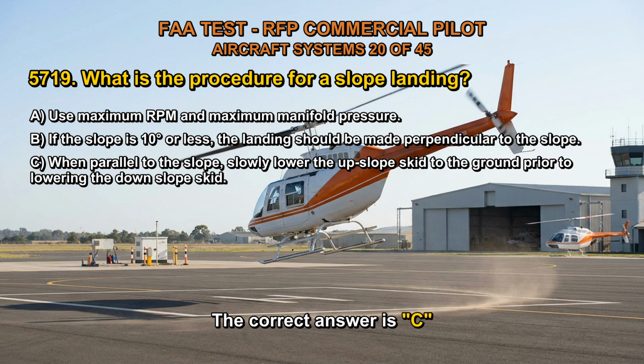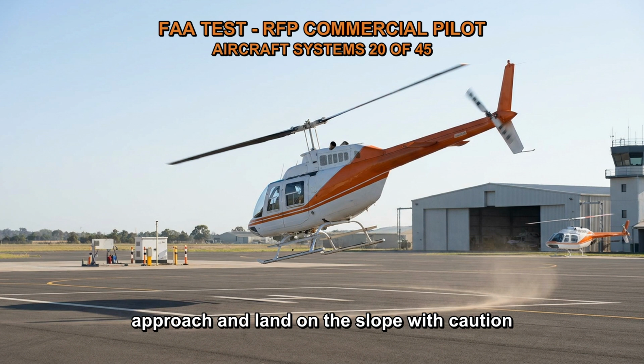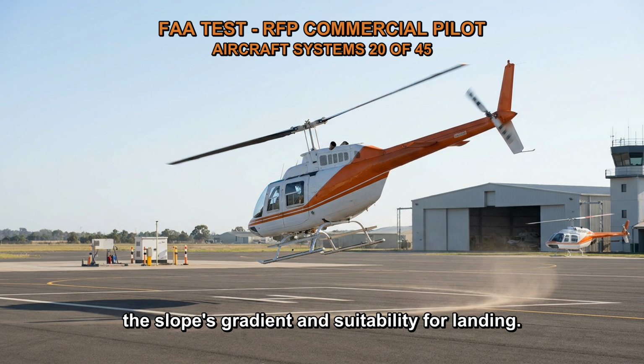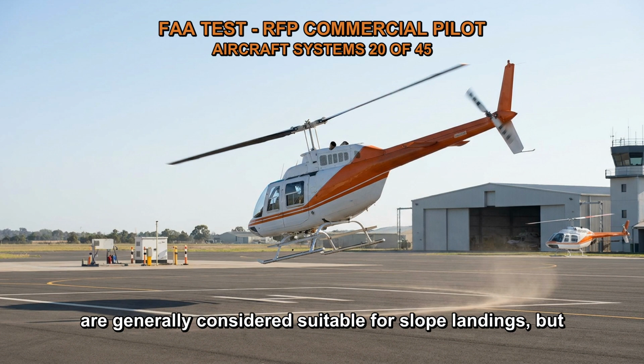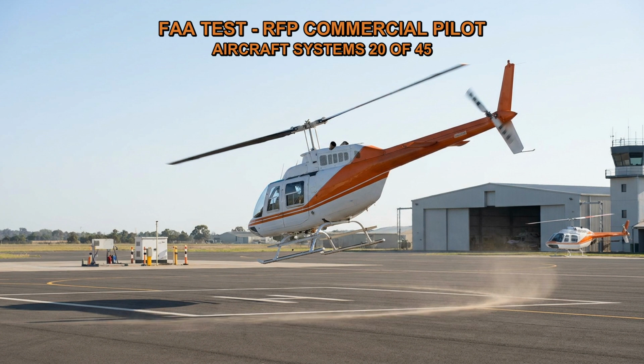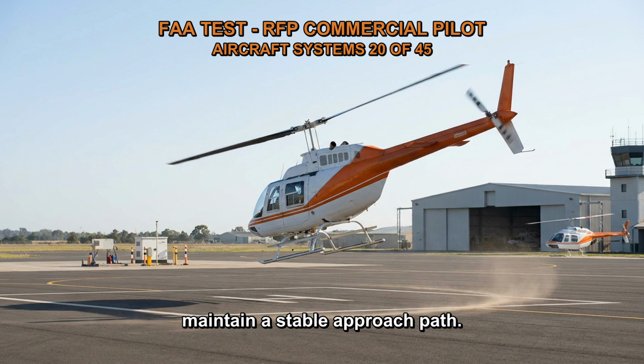The correct answer is C. During a slope landing, it is important to approach and land on the slope with caution and proper technique. The procedure typically involves the following steps. Determine the slope's gradient and suitability for landing. Slopes with gradients of 10 degrees or less are generally considered suitable for slope landings, but it's important to assess the specific conditions and limitations of the helicopter.